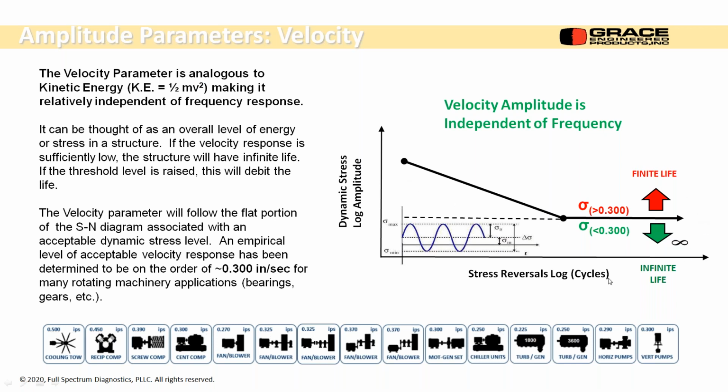If I operate above 0.29 inches per second, I'm going to have finite life. Eventually it's going to fail. So that's my alarm level. If I can stay lower than that, I'll have better outcomes on my machinery.